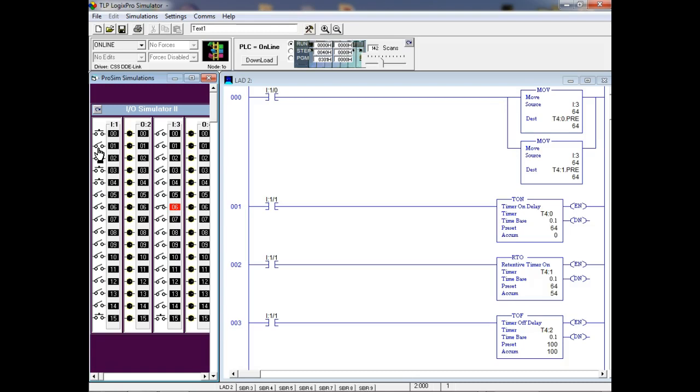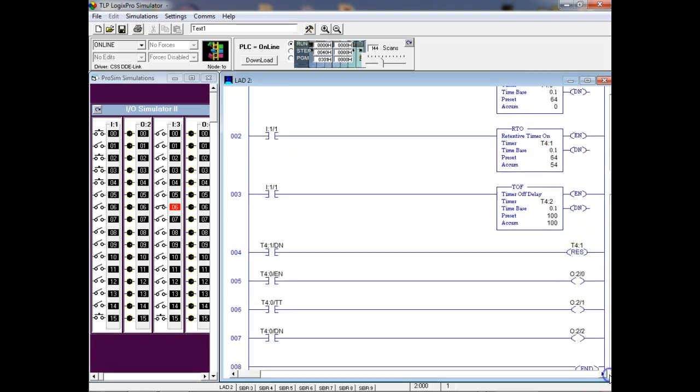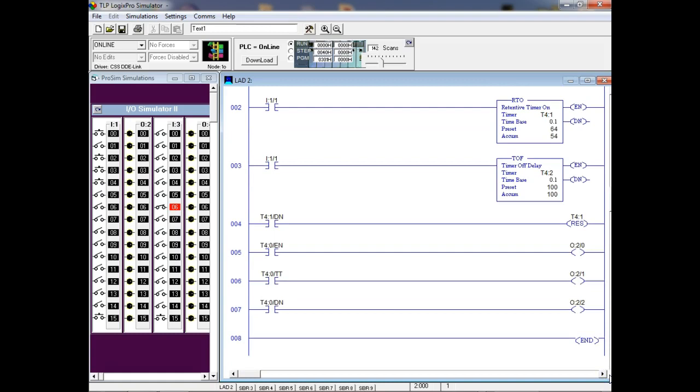So watch our registered bits we have available to us. One of them's not shown. Enable. Timer timing. What's the difference between the timer timing and the enable? Yeah. While it's timing, this guy is true. If that rung is enabled, this guy's what? True. So this guy's going to be true even when it meets its time, right? You understand that? Yes or no?